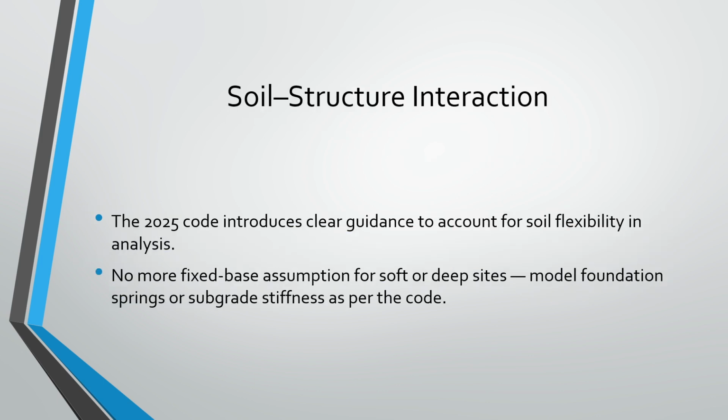And the last point that I would like to discuss in this presentation is soil structure interaction. The updated code, the revised code, gives clear guidance to account for soil flexibility in analysis. So, no more fixed base assumption for soft and deep sites, model the foundation spring or subgrade stiffness as per the code. So clear guidance is now given for soil structure interaction.